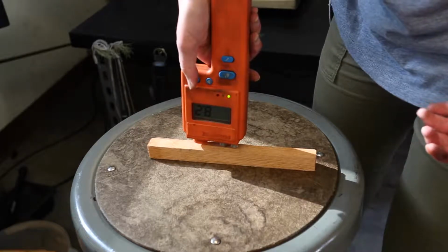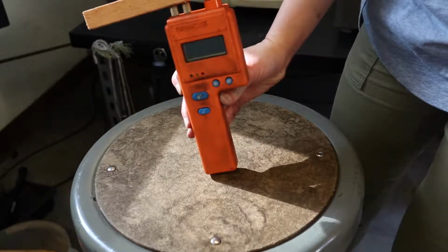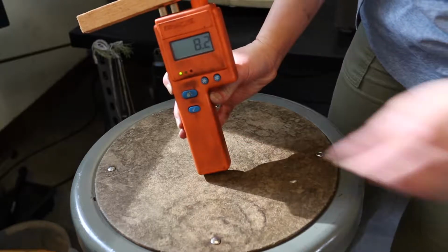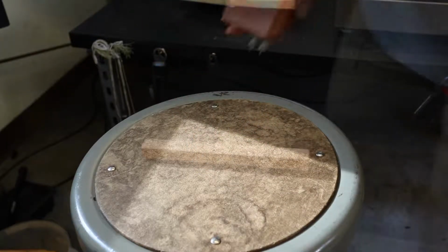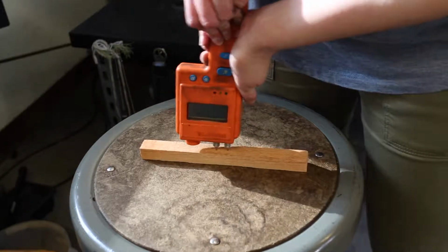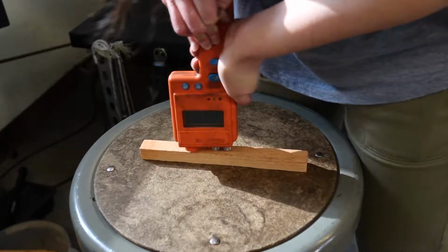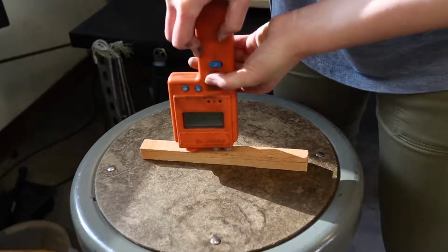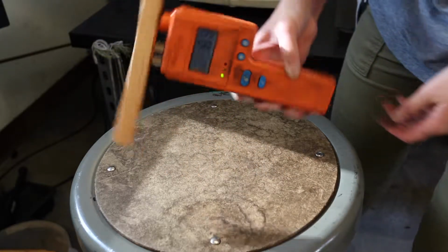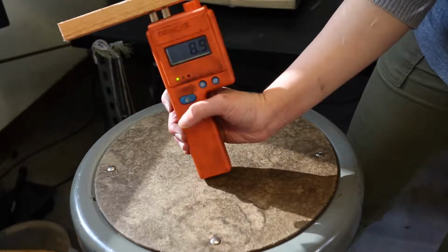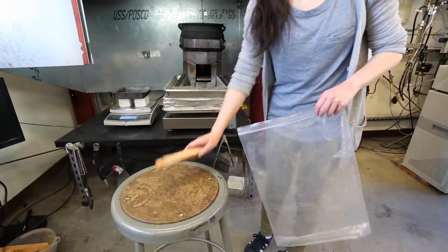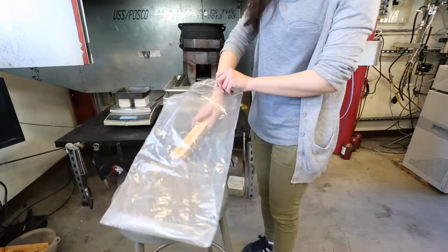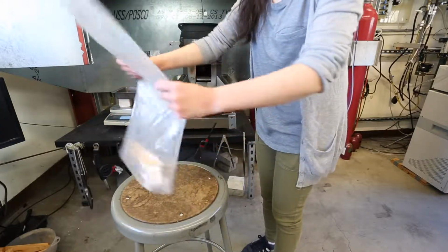We use a pin-type moisture meter to check whether the moisture content of the wood sticks deviates significantly from measurements we took a week ago in similar samples of wood, before performing the oven dry method. Because each measurement with the pin-type meter covers only a small portion of the wood stick, we take a total of 6 measurements, 3 each on 2 randomly chosen sticks. If we do find a significant deviation, we would then seal some samples inside a vapor-tight bag and flag it for oven dry analysis.